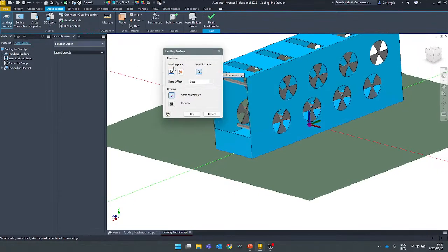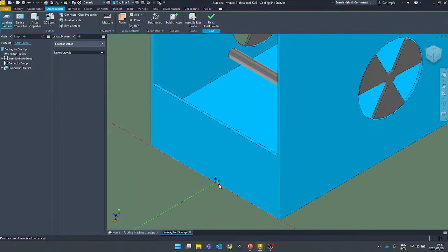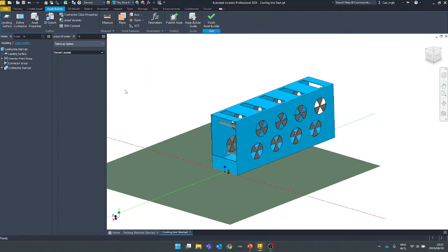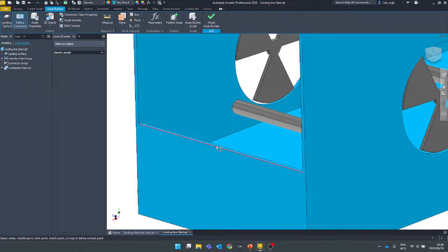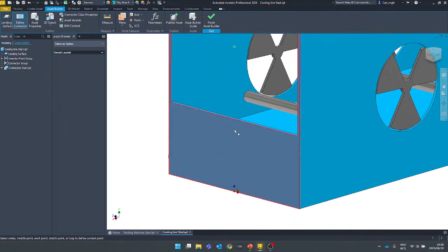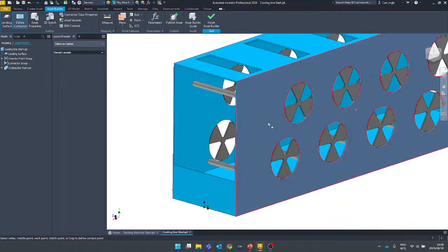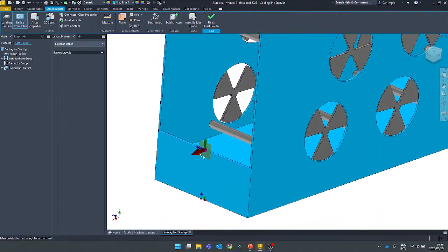And so under landing surface, we'll set landing plane insertion point, so we can see the insertion point relative to the part. And then under define connector, once you click that, it looks like nothing happens, but essentially you're able to go to your model and select either a face, a work point, or the midpoint of an edge. Basically, whatever you highlight, it's going to find a point, let's say the centroid, and that point is going to be your connector.